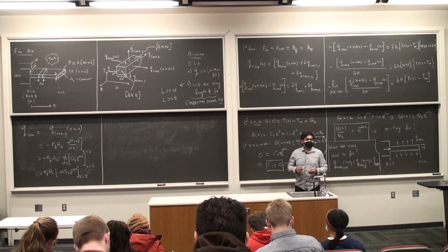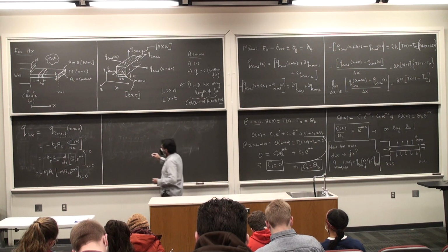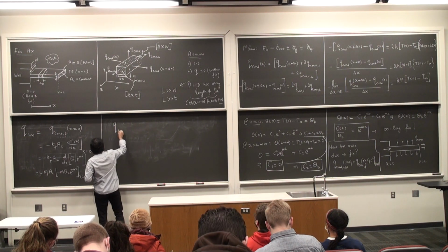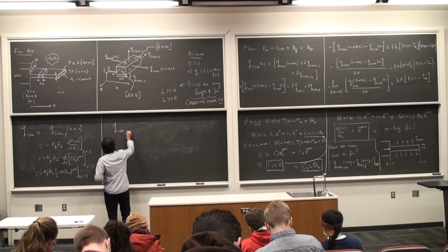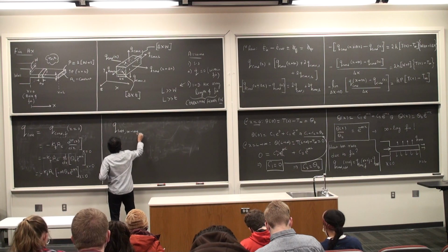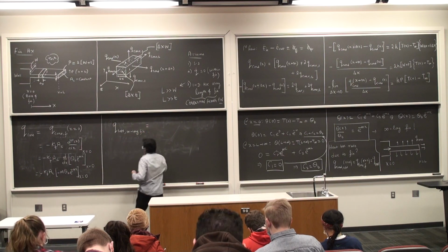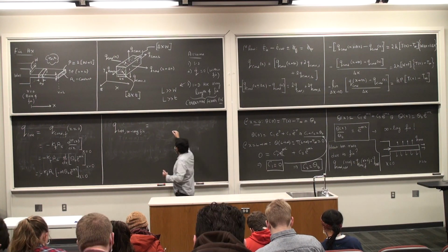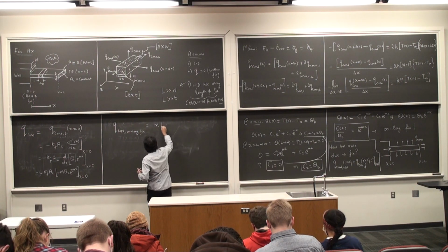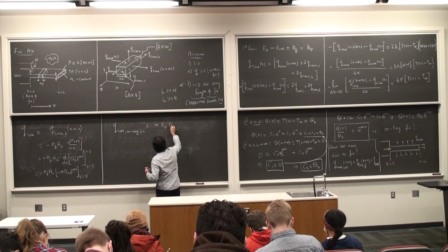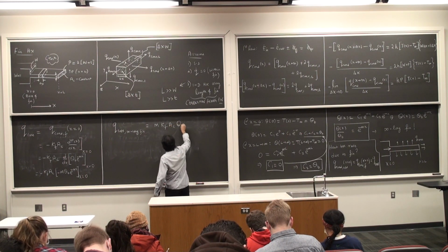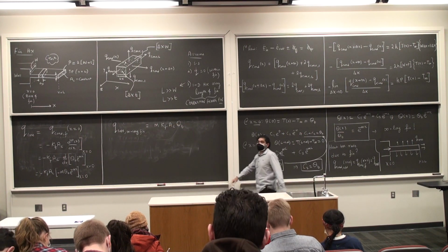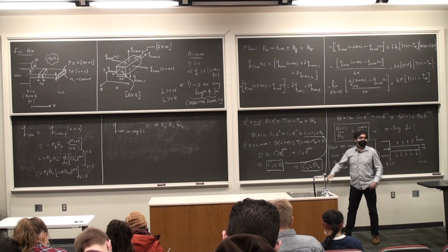And if I rearrange all these terms, I end up getting the following. So Q loss for an infinitely long fin, the negative sign vanishes because I have a minus m inside, so this is now going to be plus m kf Ac theta b. The e to the power minus mx also vanishes because I'm substituting x is equal to 0 there.